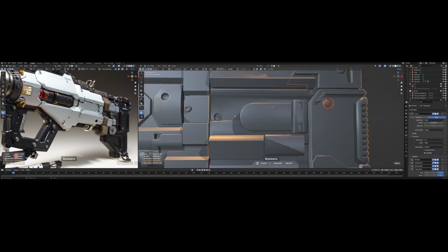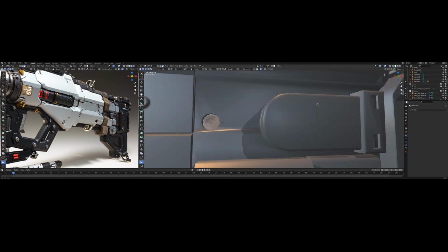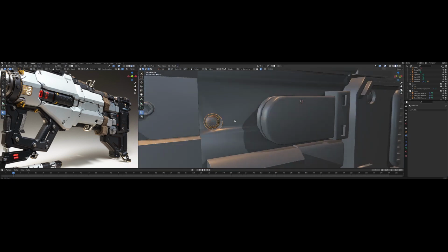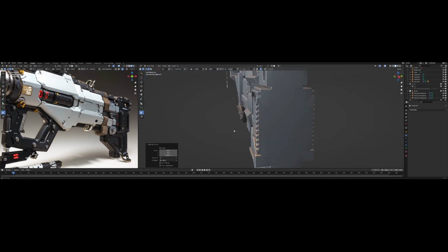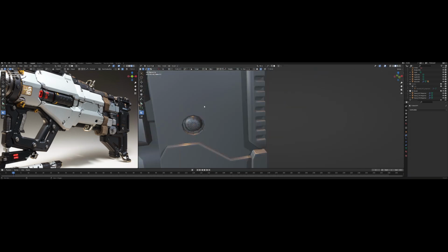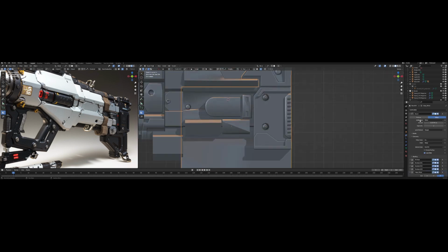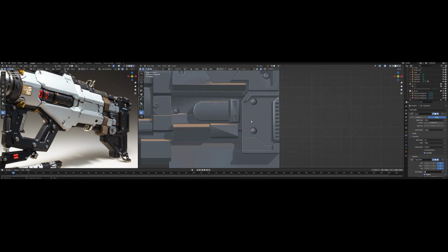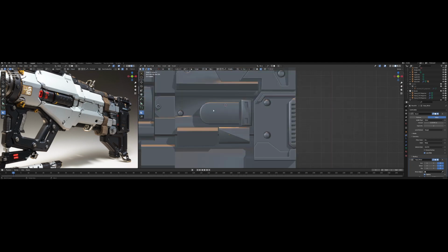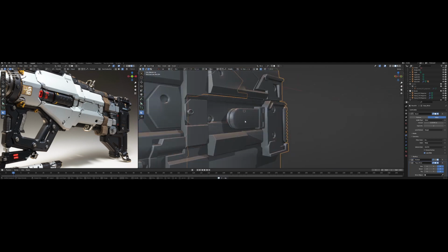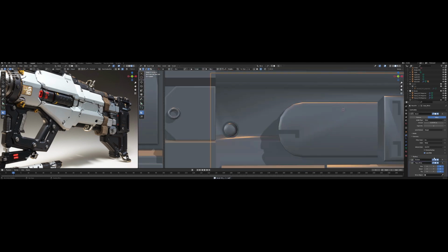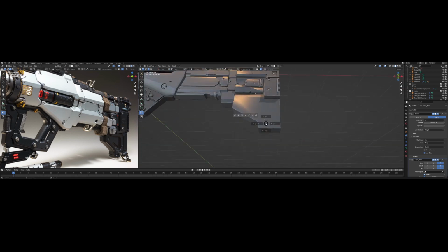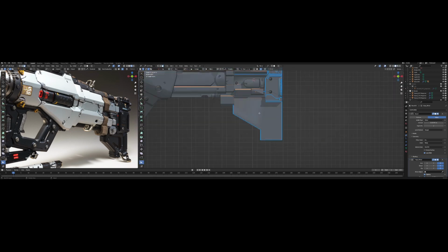If you forget to extend the joinable line to the innermost area of the whole mesh, there will be some vertices created on the edge, especially on those curved areas, which will be extremely hard for us to fix later. So that is just it.